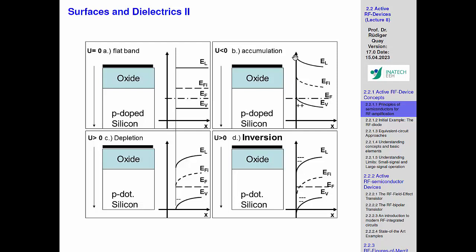What we tend to do then is that we're defining a Fermi level, which is again the occupied band, and this is at some level then, and we relate the bending of both bands relatively to this Fermi level, and then all kinds of things can happen. So, for example, if the Fermi level cuts the valence band in this case, then we have carriers really at the interface, but not fixed carriers, but attracted carriers, so to say. So that is one way.